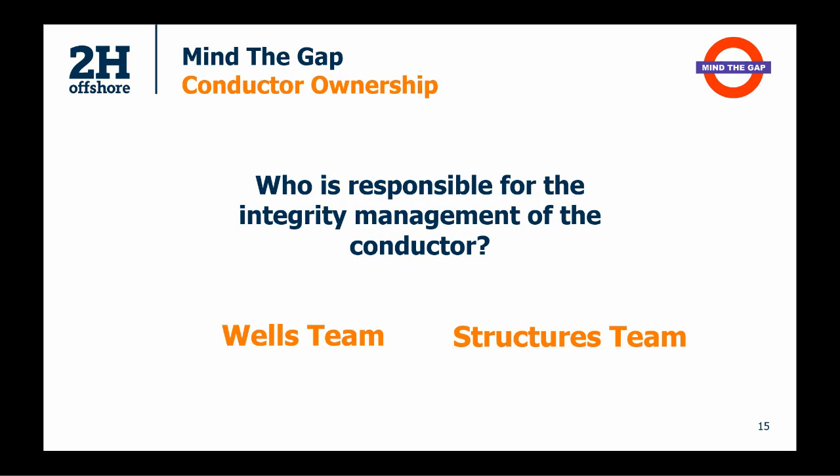So there's justification both ways. Yes, you could argue it should be the structures team. The conductor is often the structural member. It's supporting the well, it's supporting the surface equipment. It's also interaction with the platform structure. So yeah, it's very structural in that aspect. However, a well is just a series of concentric pipes, and the conductor is one of those concentric pipes. And as we've shown, the thermal loading downhole actually has a significant effect on the conductor on the axial state. So it's very much part of the well.